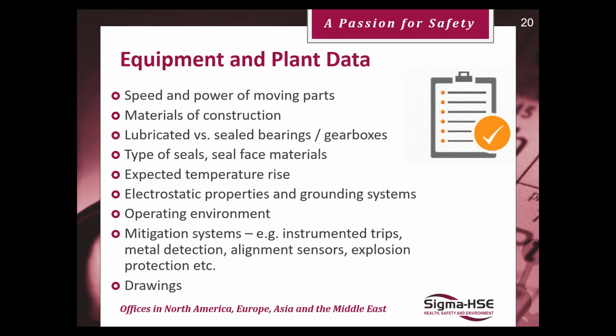So yeah, I'm beginning to do my NIRA assessment. First, you have to collect a lot of information about the equipment. So typically this is the manuals, the drawings, and especially the speeds of the moving parts. So the speed is linked to mechanical sparking. Typically if your rotational speeds are less than 1 meter per second, mechanical sparking as an ignition source can be ruled out because it's slow moving.